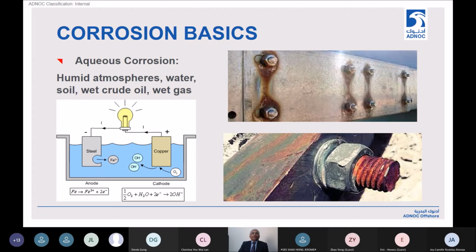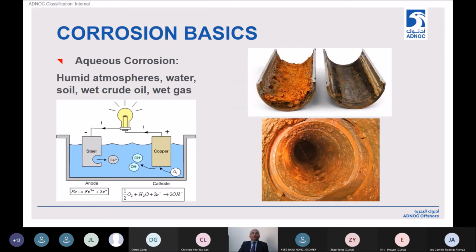So this is a typical electrogalvanic or electrochemical reaction. Examples of atmospheric corrosion, where fasteners tend to corrode because their external surface coatings are damaged. They can result in disastrous failures of structures if the fasteners lose their ability to hold pieces of material together.